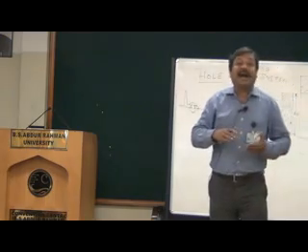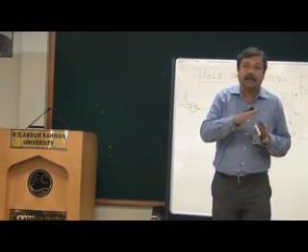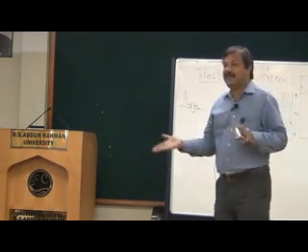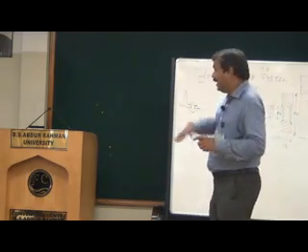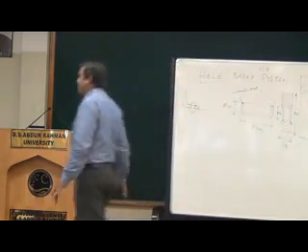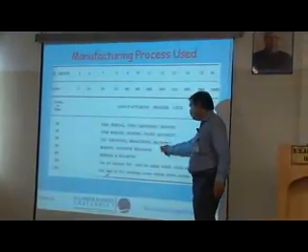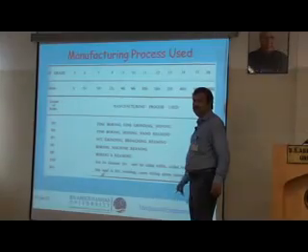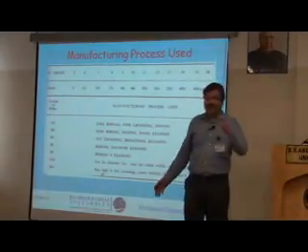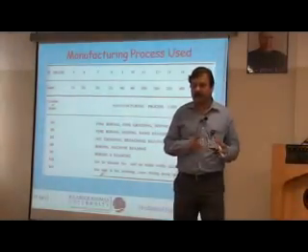So I get whatever fit I want by controlling the shaft dimensions. By varying the shaft dimensions, I will be able to get whatever fit I want. So most of the holes will have the H7 tolerance and the shaft dimensions are accordingly controlled.